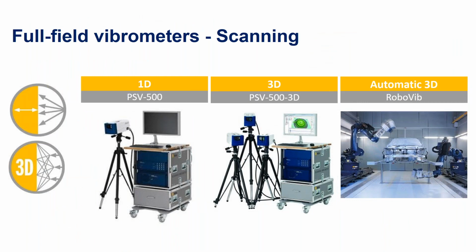The scanning vibrometer has the capability of mapping out the vibration. So we can scan, map out, and display the vibration mapped over an area as a 3D animation. We have this as a 1D scanning vibrometer that can map out a plane. This is commonly used for acoustics because we look at the out-of-plane vibration on a circuit board. That's what you want to look at for looking at vibration. We also have a 3D vibrometer, which can measure X, Y, and Z vibration.